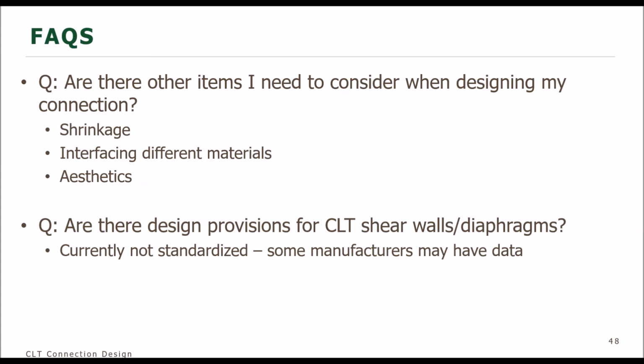Yes. And just two more questions. Sure. One, could you clarify using the C sub D factor in your example? I think there was a question that came in. Oh, yes. So I actually did not use C sub D, the load duration factor, in my examples because for both of my examples, I was calculating only the unadjusted reference design value. So I did not specify a load duration or type of load.